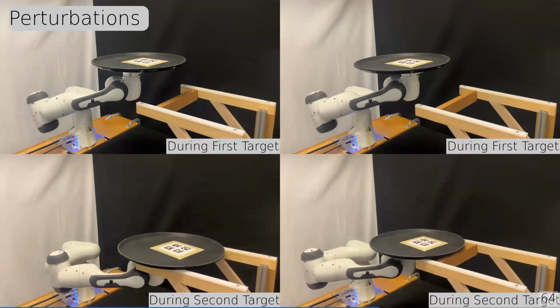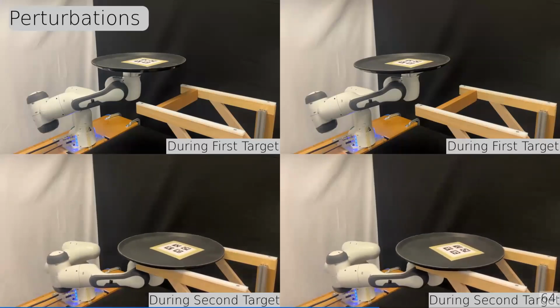So all you're doing is physically perturbing the state of the tray, and you're limited by the perception system, right? Your April tag, you said it was 10 hertz? So you're updating the state of the tray at 10 hertz, your MPC is running at 30-60 hertz. So your controller is running faster than the perception. But if the perturbation were on the body of the robot physically, would you be able to recover from that?